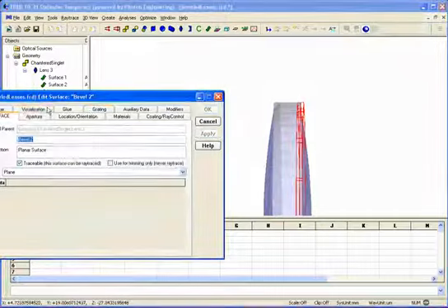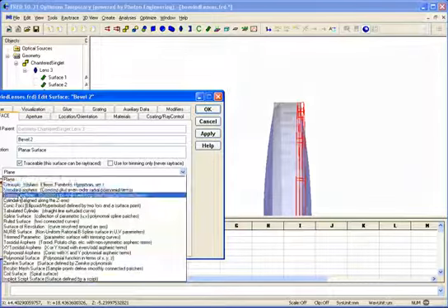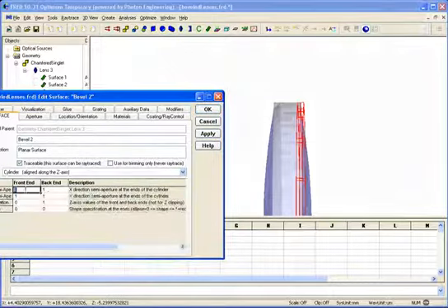We're going to do the same thing for the rear bevel surface. Change it from a plane to a cylinder. Yes, I'm sure. The front end now is going to be 20, so it's decreasing in height. The back end goes to 19. The Z location is going to go from -1 to 0. Remember, the bevel is starting at the plane of the rear surface here. So hit apply.